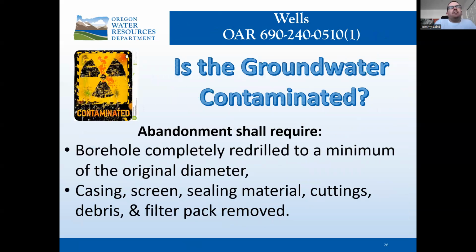So what happens if you're on a site where the groundwater is contaminated? Abandonment shall require that the borehole be completely re-drilled to a minimum of the original borehole diameter. The casing, screen, sealing material, cutting debris, and filter pack must be removed.